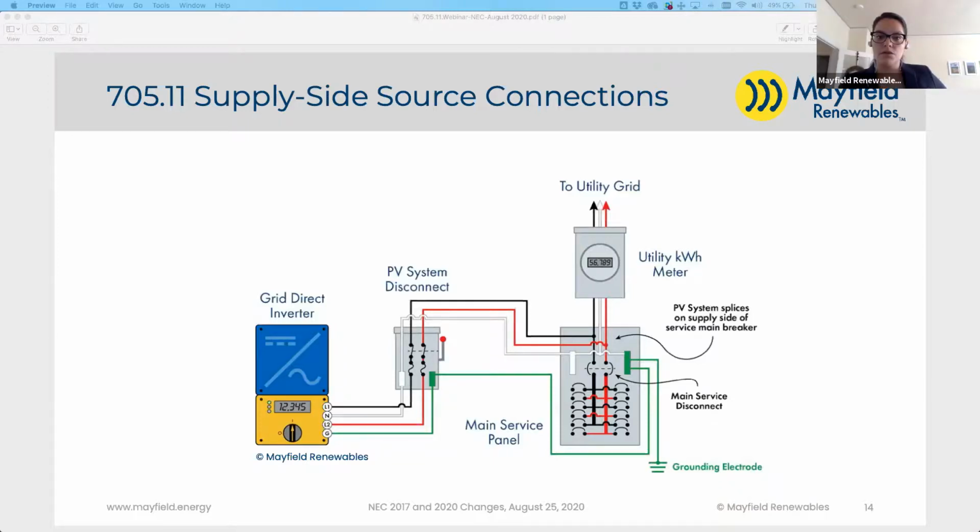And we're going to move on to the next question, which touches on temperature, selecting the appropriate temperature to use. So the industry standard for site temperature data can be a lot of times 2% ASHRAE high temperature, which is the most commonly used. Some places require you to use the 0.4% ASHRAE high temperature. I know the ETO requires that on a number of things. And then there's also the highest temperature ever recorded, which would be the most conservative calculation.